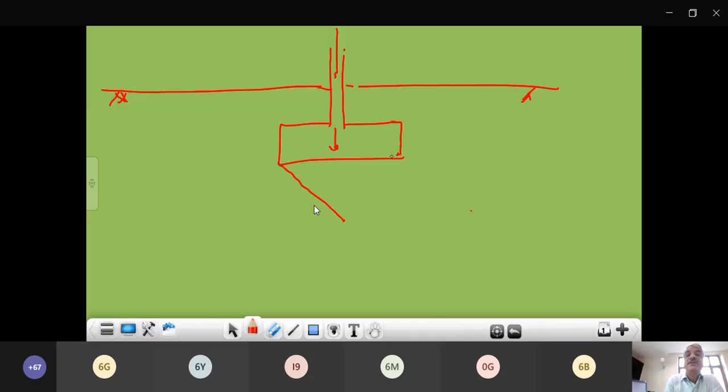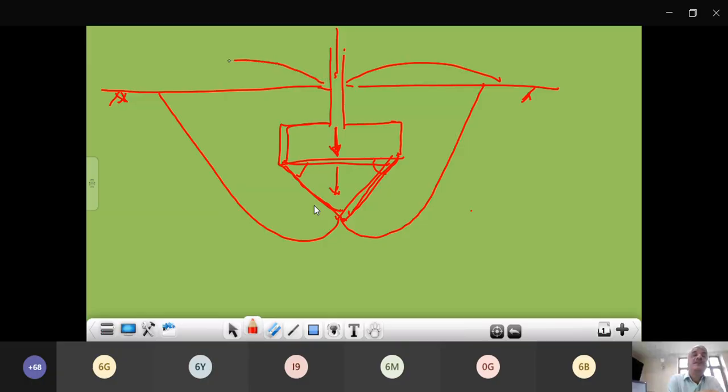In general shear failure, at the load equal to bearing capacity, this footing will sink like a punch. There will be a sudden failure with some portion of soil in a triangular wedge. These angles are also given there, 45 plus or minus phi/2. This portion will remain part of the foundation, and then there will be two well-defined shear planes. Their geometry is also given, and then there will be heave on the surface, and a sudden failure. That is called general shear failure.